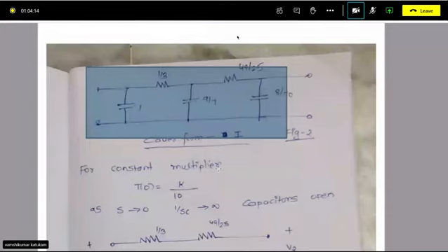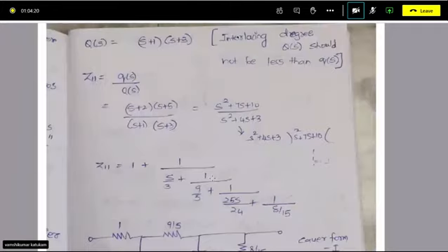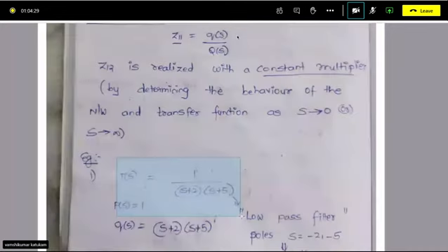So this is about form 1 by Q of s. Similarly, this problem I discussed is simple, of the form 1 by Q of s, right? If you have in the numerator s or some zeros, s square, or s plus some values, that is, some zeros are present, how to obtain that case, you will see in the next class. So this is your low pass filter. So you have resistor, capacitor, and if you take the output across the capacitor finally, it is a low pass filter.